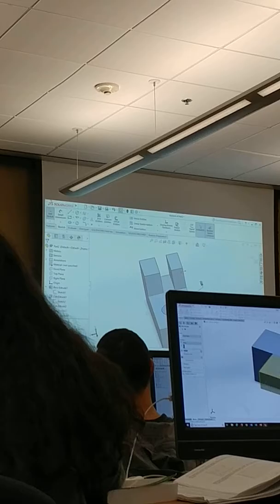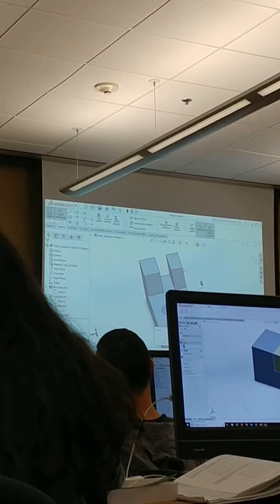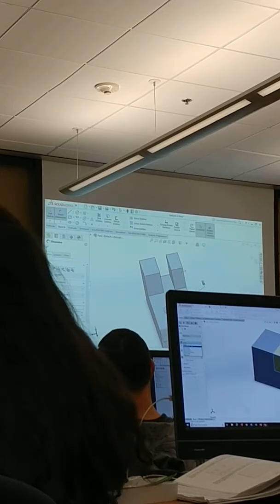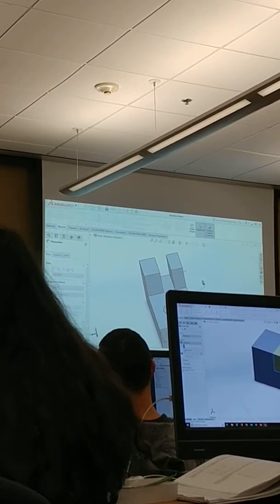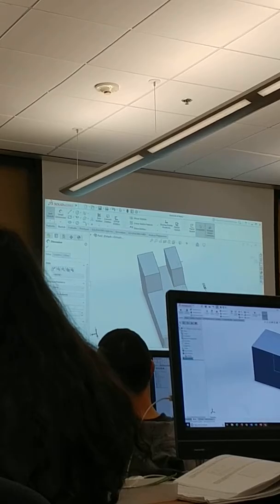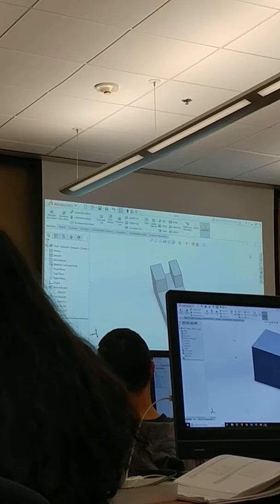So what ends up happening, well, if this is in the center, I want it to be this same distance. So I go over here and I measure this from this edge to that center, and I say it's 5, let's say, for instance. And I measure from this end to that end, and I call it 5, and look, the hole goes black. So now I know that I'm fully constrained, we're good, it goes through.